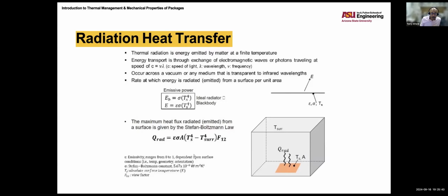So we look at an example here. Surrounding temperature of the box, 35 degrees C. We're emitting again 100 watts, 0.24 meters squared, the PC board that we had. And we're assuming that the emission is through a board. We got 100 watts, and then enclosure at 35 degrees C. Surface emissivity is 0.7. The view factor is 1.